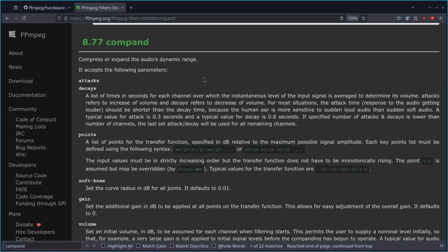Which means if you have noise in your audio, and you applied the traditional compressor with just applying gain first and then compression, you would have the noise because you're applying gain, so your noise would get louder. And then your compressor would just be compressing down the tops again. So your noise would be there. You would have to push your noise down further. But with this compressor and expander, your noise will show up and disappear sometimes, depending on how loud your input volume is.